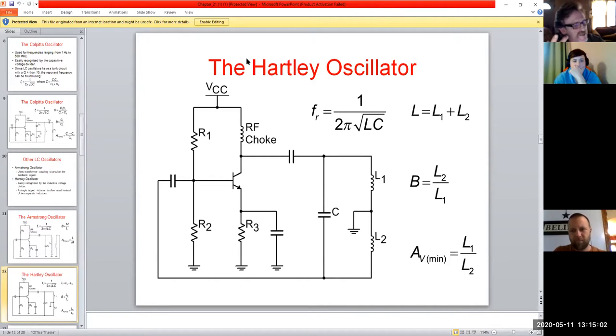Now, when you look at like the relationship, how does it like to look at it? And this is where something they call the superposition theorem comes in handy, because when you look at superposition theorem, what you would do is take your two voltages, if you will, and as far as the circuit is concerned, you would get rid of your voltage source and put a ground there instead and analyze the circuit.